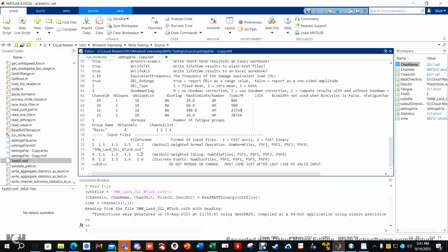Okay. So with that, then you'll notice on yours it says DLC 2.3.1 or something .out. Just change it to match your out file. File format, 1 for the FAST ASCII or 2 for FAST binary. You could switch it to 2 and use the .outb, but I prefer to use the .out file. Okay, so now, hopefully, when you run it, there shouldn't be any errors.